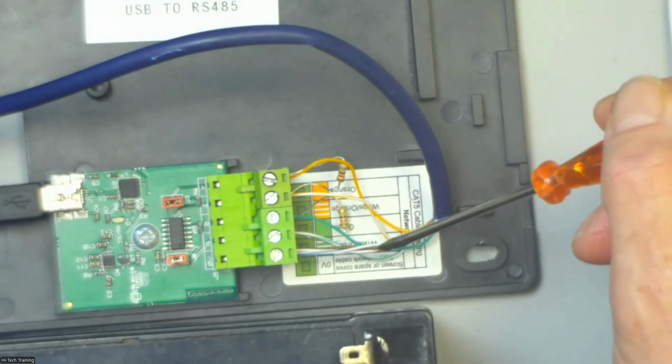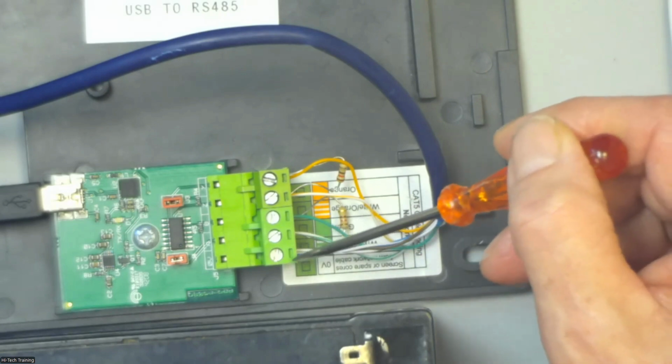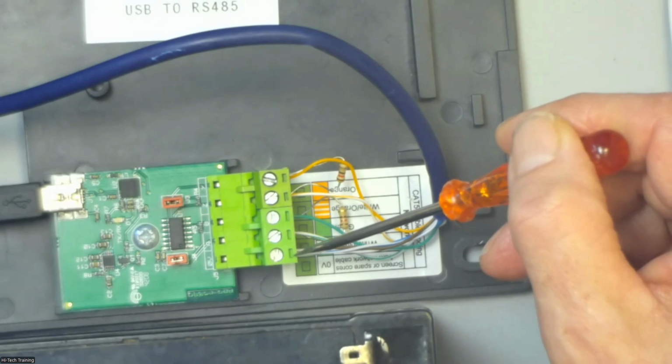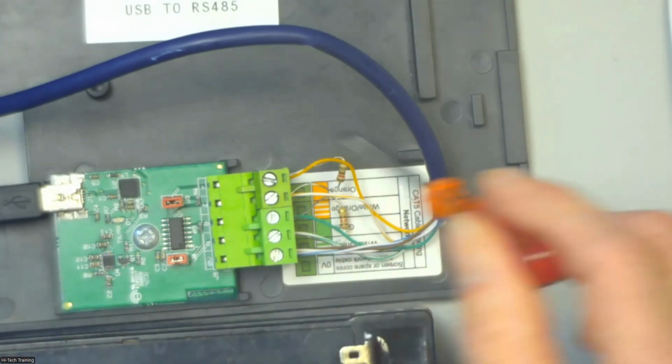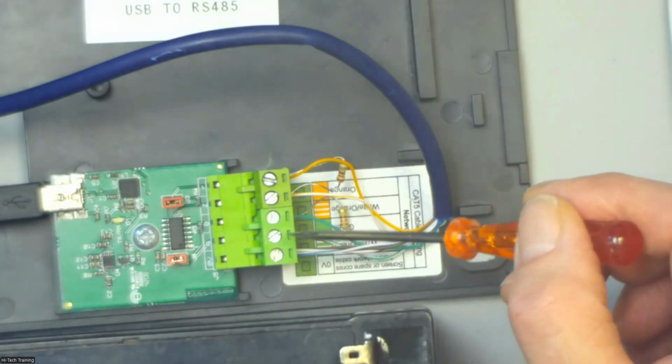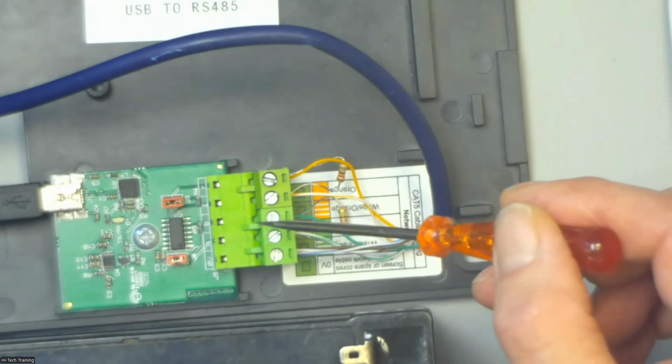Here, any spare cables or earth cables or sheets or screens go into this last termination to get rid of any electrical noise. So here we've got USB, which talks to the computer, and over on this side we've got the RS485, recommended standard 485, to talk to the door controller. So that's that unit there.